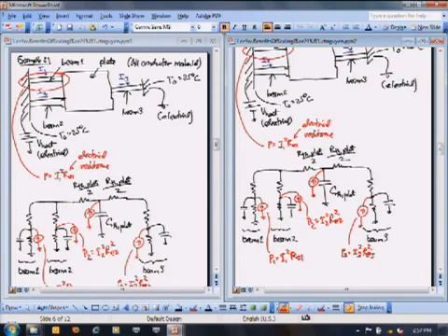So let's go ahead and do that. First of all, each of these beams, just dimensionally, I didn't give you dimensions, but if you think of dimensions according to what you're seeing here, these beams are much smaller than that plate. That plate is dominating, and that's what you're going to see time and time again in many MEMS structures. And so in that case, if the plate dominates, there's no need to include the thermal capacitance of the beams. In addition, just like we did last time, the plate has a lot of width, so its length to width ratio is not as big as that of the beams, and so these guys I'm also going to neglect.